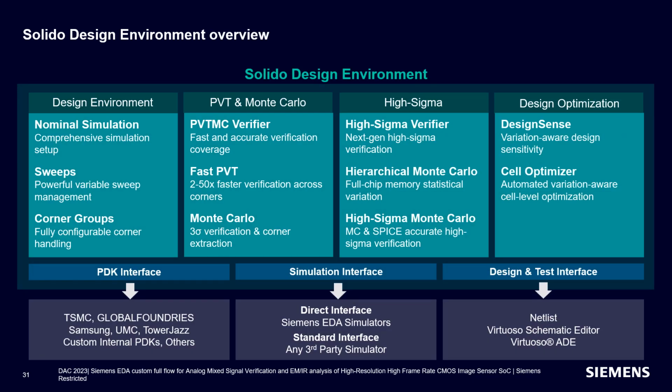Solido design environment not only provides a design environment for performing transistor level parametric simulation, there are also powerful tools like PVT-MC verifier for doing up to 50x faster verification across corners for 3 sigma verification.